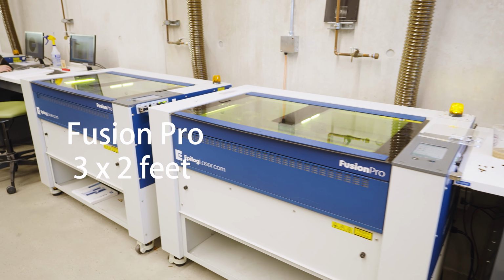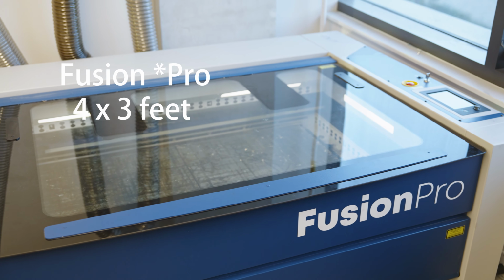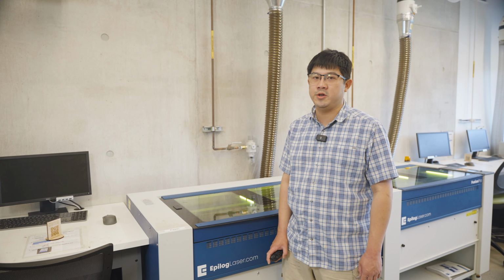We have 3 Epilog Fusion Pro laser cutters available for people to use that can cut up to 2 by 3 feet, and 1 Epilog Fusion laser cutter can cut up to 3 by 4 feet sheets. Our 3 smaller machines also have fiber lasers, which are more specialized in their uses. The fiber laser is a different frequency than the CO2 laser, which allows it to engrave metal and cut very, very thin sheet metal, such as copper tape and aluminum foil.